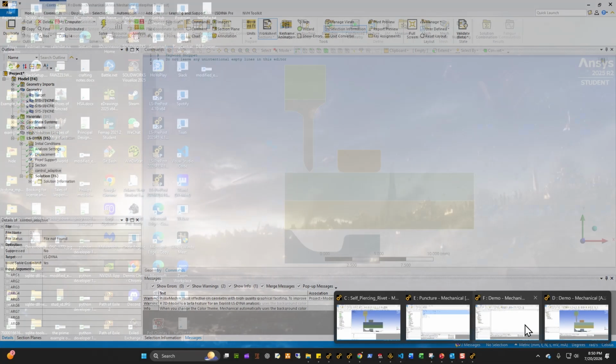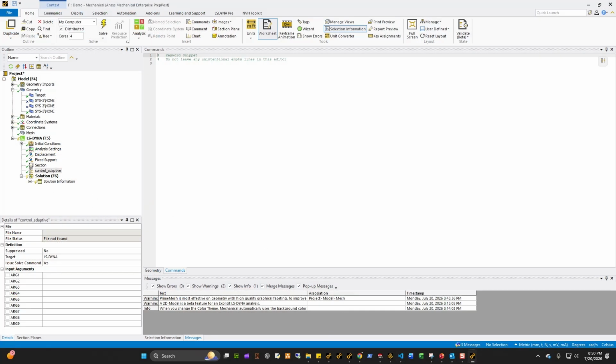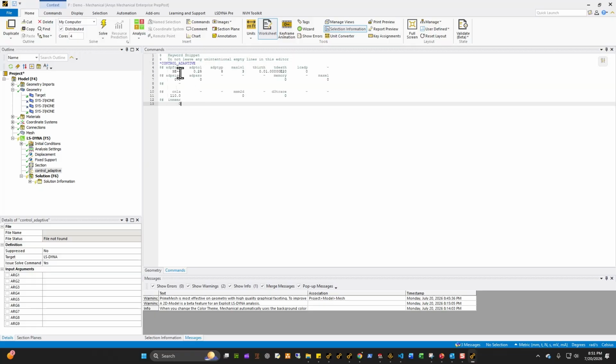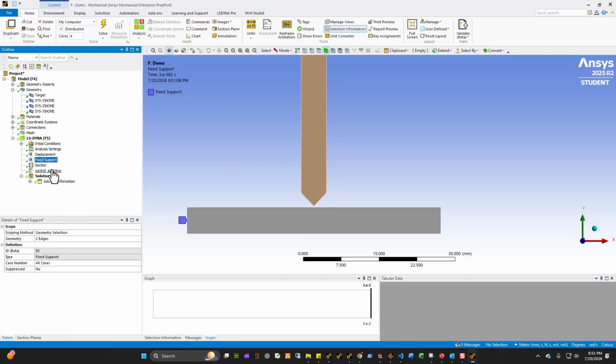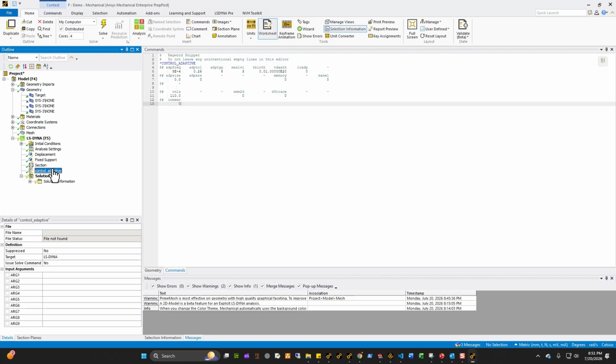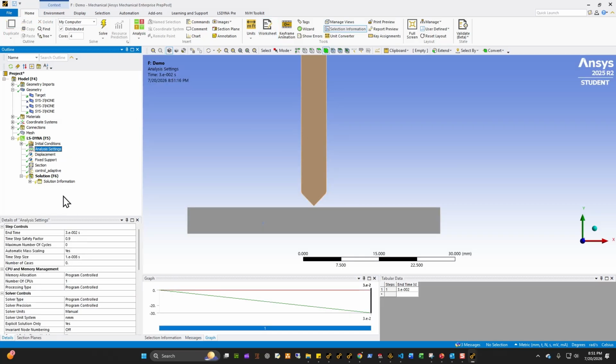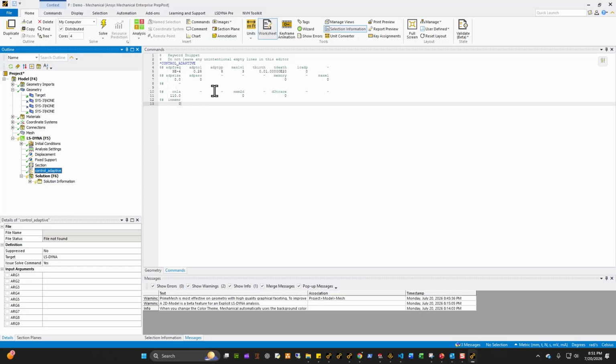What we do here is that in the keyword template, I wanted to use a frequency of 3e-4, over a total duration of 3e-2 seconds, which means it's gonna rematch it 100 different times. My adapt frequency is 3e-4, and my total duration is 3e-2. So every 0.0001 second, I'm gonna try to rematch the body. Every 3e-4 seconds, I'm gonna try to rematch the body. I'm gonna rematch it 100 different times.